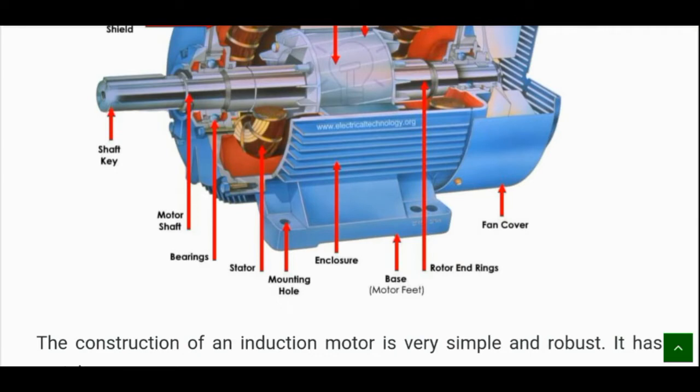And these are enclosures through which air can pass and cool the motor. This is the mounting holes, and this is the stator, and this is the place of the bearing through which the motor can move smoothly, and this is the motor shaft. Okay, this is the construction of the induction motor.